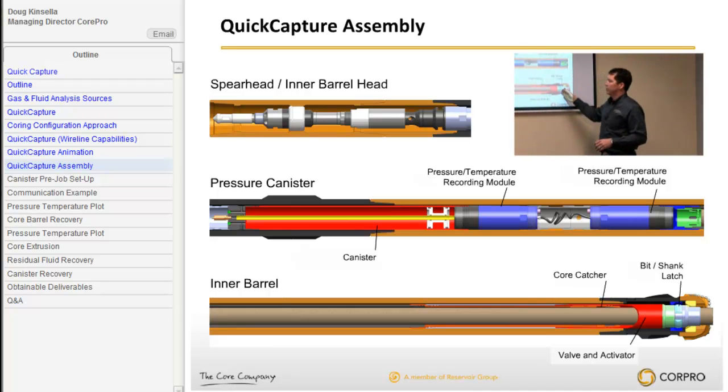But if the valve leaked, it could migrate the other way, and we would never really see. By installing a pressure relief valve, we actually create a pressure inside the chamber. If that pressure on the plots, when we get to surface, was declining, we would know the valve was leaking. So it's a way for us to communicate to the customer that, listen, we know the chamber was sealed.